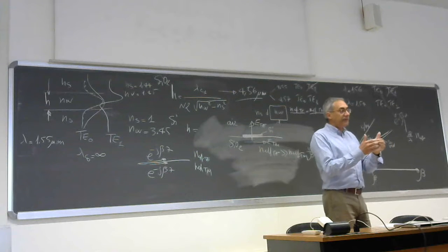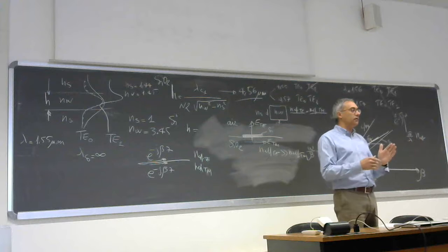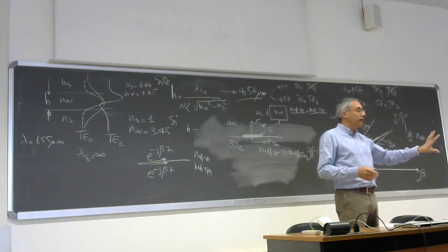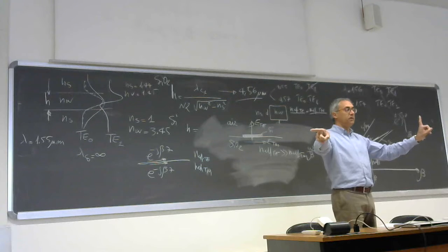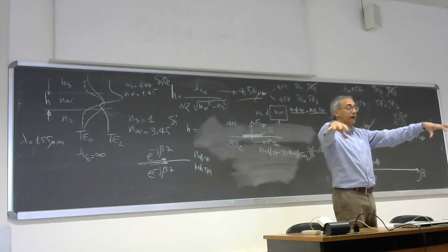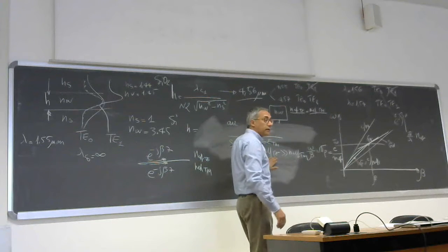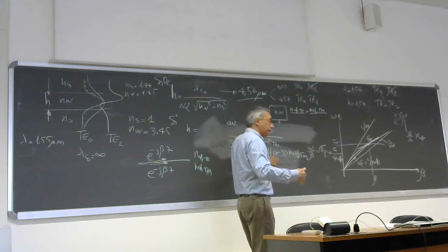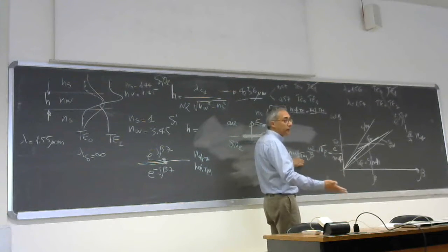At the end of the optical fiber, you split the polarization in two. So you send the vertical polarization on one side and the horizontal polarization on the other side. Okay, so you have the TE and the TM mode. Then you put two physical devices, one designed to work properly with the TE, and another one designed to work properly with the TM.